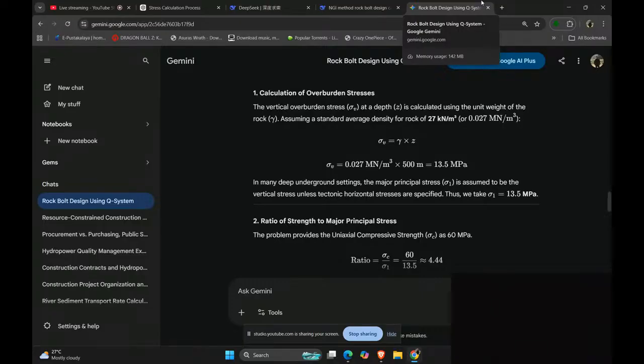Similarly, support with systematic rock bolts 4 meters long with 1.5 to 2 meter spacing in the crown and walls, and 50 to 100 mm of shotcrete in the crown and 30 mm on the sides, is required. Rating adjustment for discontinuity orientation for favorable conditions is -2.